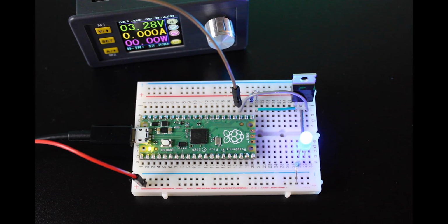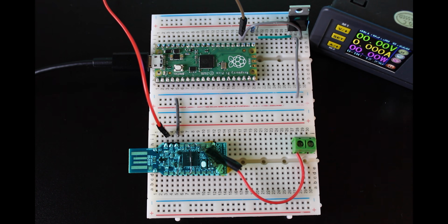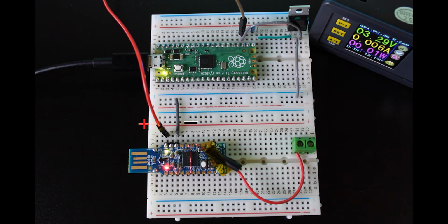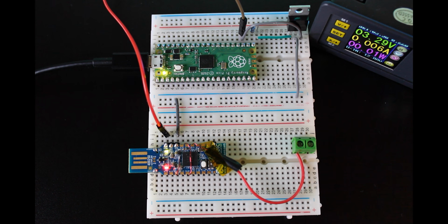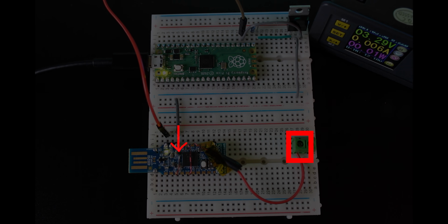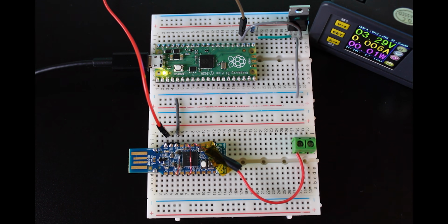And this is the whole setup that's required to perform the glitch. Here's our external target board, and we have now simply connected the ground line from our LED before to the ground line of this target board, which means we are controlling the power line of this target board. But we do not want to glitch the core voltage of this board, we want to glitch the voltage of the CPU line. Therefore I have added this single wire to all of these boards. We are changing this cable to this location here, which means we are grounding the core voltage line of the CPU by toggling this pin.